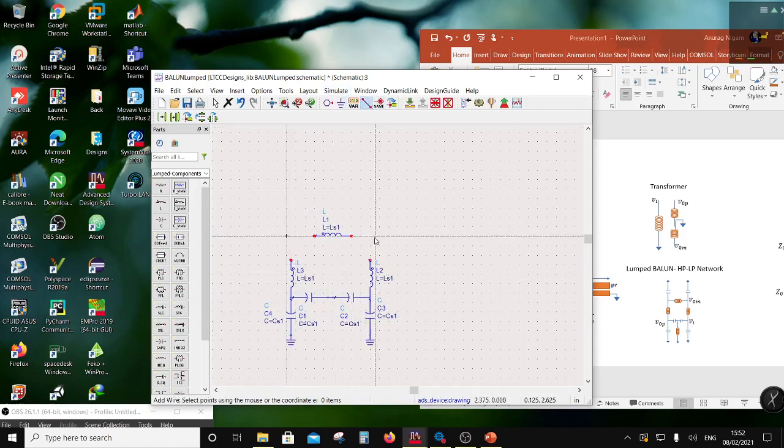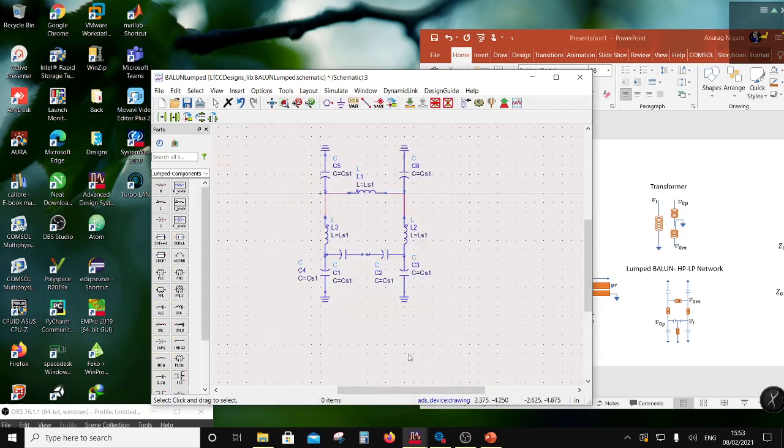Now, for the low pass section, there are two shunt capacitors, right? One on the input side, the other on the output side. Now, if I was to do the analysis, I can assume that these two come in parallel. So the net capacitance over here is twice CS. So that's that. Okay. And then there are ports where, okay, there is one inductor which I forgot.